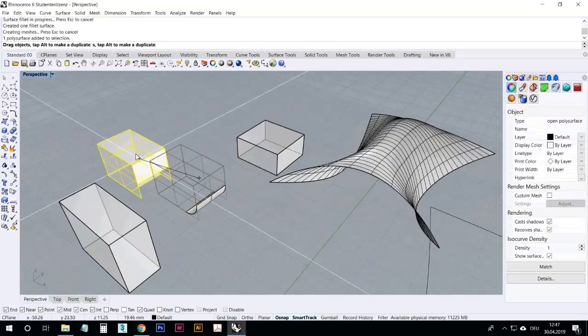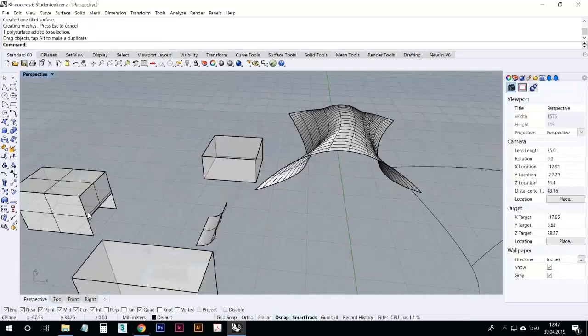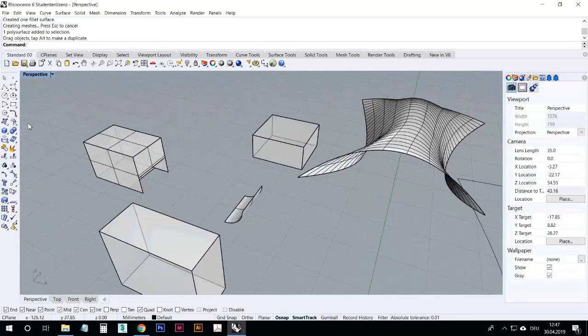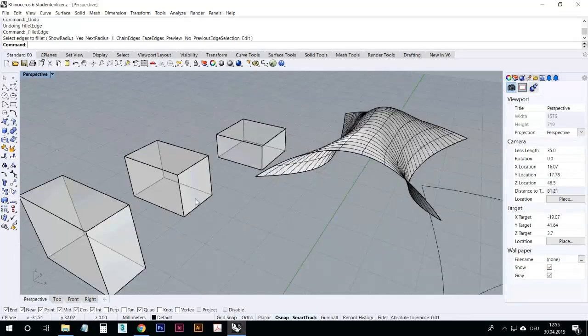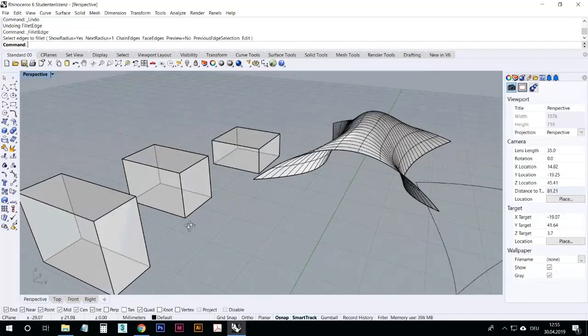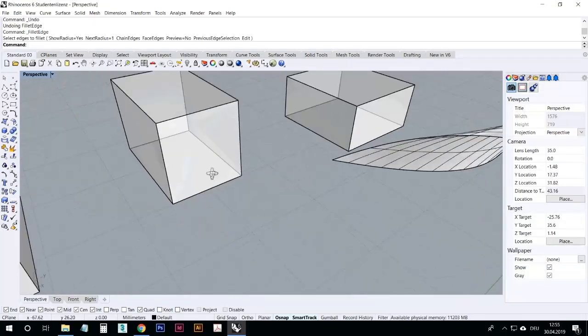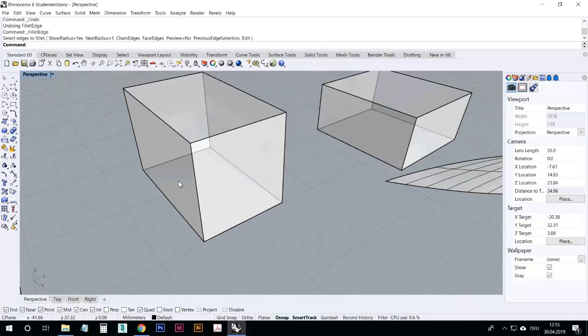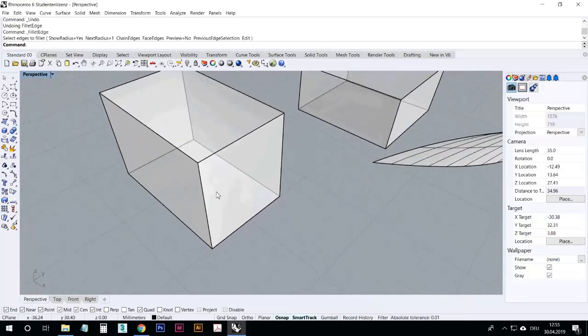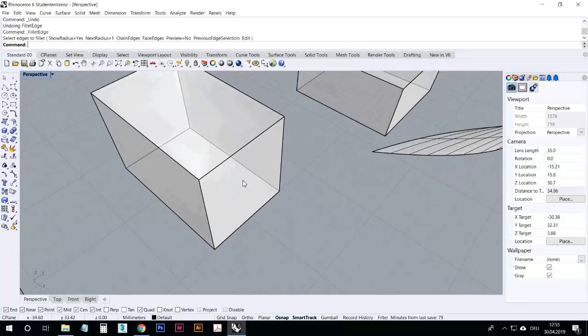Now, of course, this is a bit weird on this very shape, but you can do it on all edges, of course. So you could do such blends on fillet on the edges, so you can make the whole corner actually, and not like we did before, which was a test only on surfaces. So if you go to the solid tools and open them, you can find fillet edges right here. And edge, what is edges actually? Well, that's the side where the walls meet each other here. And the walls are not called walls really on a geometry, it's called faces.